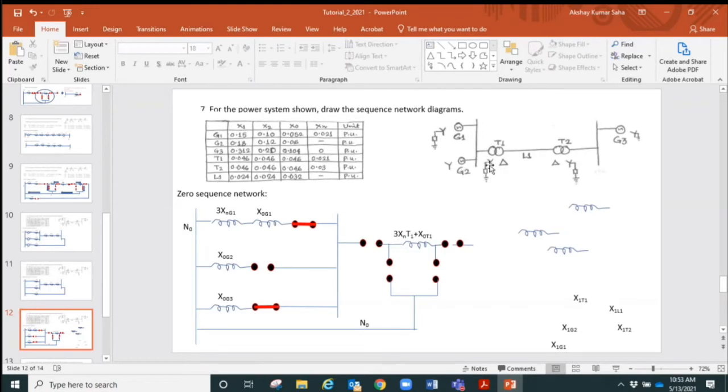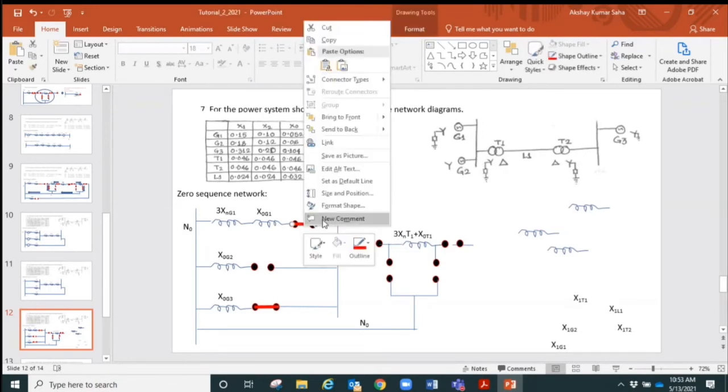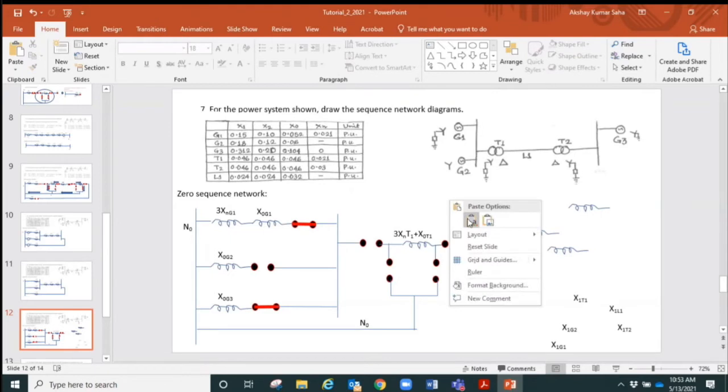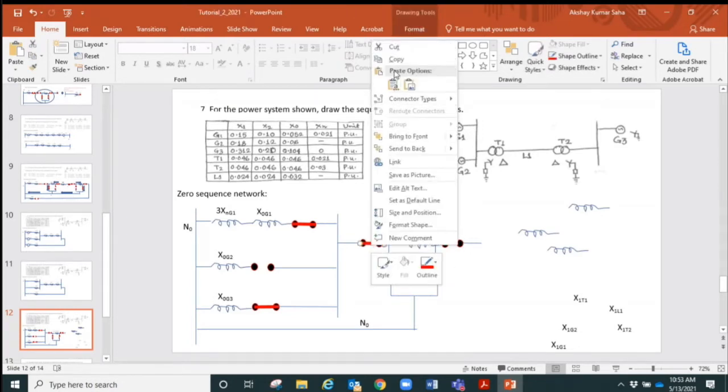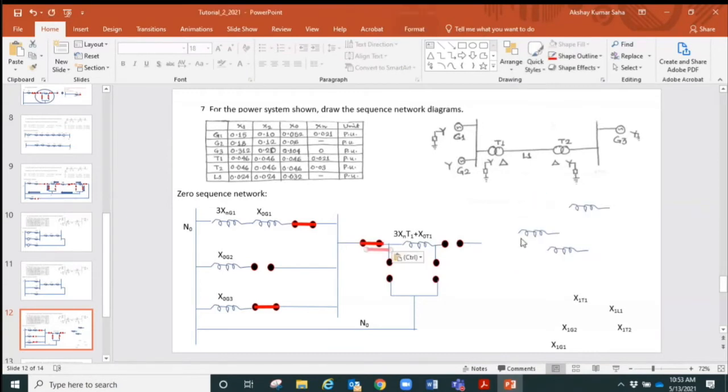And then this primary side, this side is star connected grounded, so this switch now needs to be closed, and it's not delta connected, so we leave it open. We go to the other side, it's not star connected grounded, so we leave this series switch open. It's delta connected. What we need to do, we need to close this switch. So that's the transformer 1.